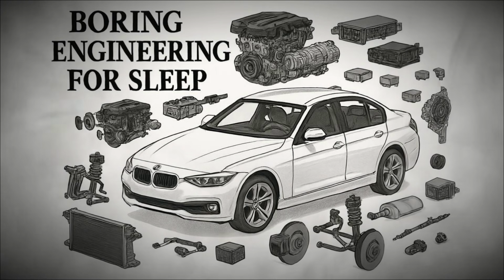Airbags complement seatbelts by providing a cushion between the occupant and the hard surfaces of the car during a collision. Airbags are fabric bags folded inside compartments in the steering wheel, dashboard, seats, or pillars, and they are triggered by sensors that detect rapid deceleration. When a crash is detected, an inflator ignites a gas-generating chemical, producing nitrogen or another gas that fills the bag in less than 1/10 of a second.